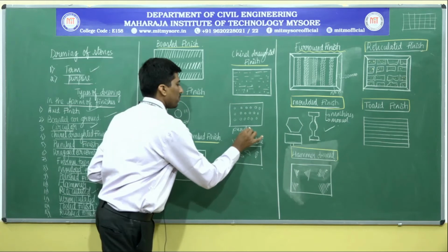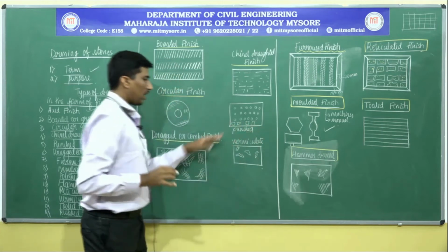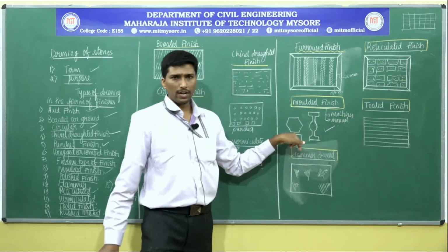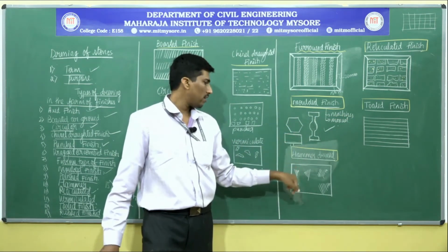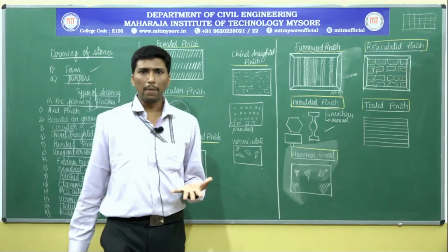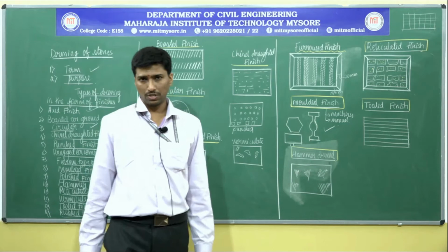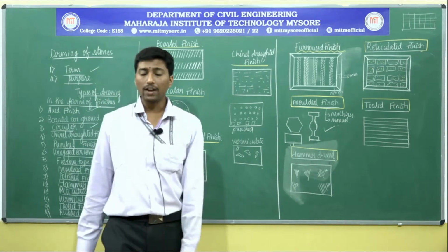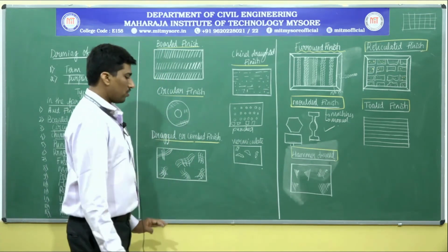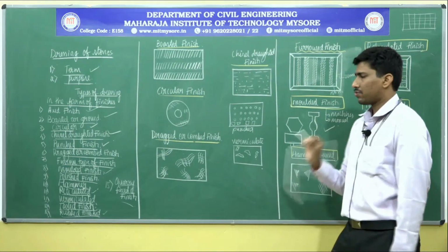Punched type of finish may also have some part of the articulations in it. Vermiculated, furrowed type of finishing, reticulated, tooled, molded, whichever size or shape has been required, and hammer-dressed, using the hammers, especially in the case of making coarse aggregate or for the usage of rubble stone masonry. There the hammer-dressed kind of rocks or stones are utilized. Okay, so this is regarding the types of finishes normally carried out.